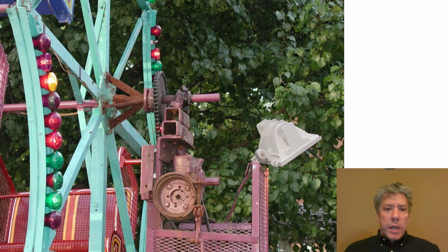Here's a bearing on an amusement ride that I don't think I would get on as soon as I saw the bearing. This is a simple pillow block bearing. You can see that this thing has significant misalignment, and it's seen better days. It's time for it to be replaced. Some interesting features here, though, that we'll approach later when we talk about pulleys and sprockets and so forth. You can see that this has been jerry-rigged, and like I said, I don't think I would ride this thing given the condition of that bearing.